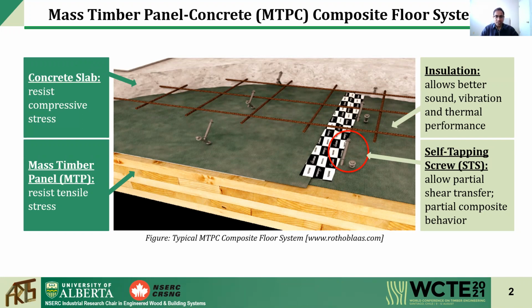The common fasteners used in composite floor systems are self-tapping screws as mechanical connectors, which are ductile. There is a substantial increase in strength and stiffness of the connection when they are inserted at 30 and 45-degree angles compared to a 90-degree angle to the surface of the timber.